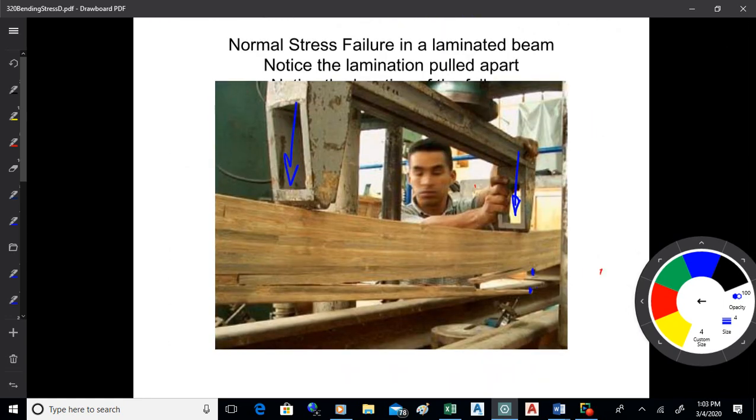Okay, there you see a beam being loaded on a jig. You see where that stress starts to fail the beam. They just pushed on that thing till it failed, I imagine. You see that crack there starts to propagate from the bottom. That's a tensile failure as they push down on the beam with that hydraulic press. And then it works its way up through the beam.